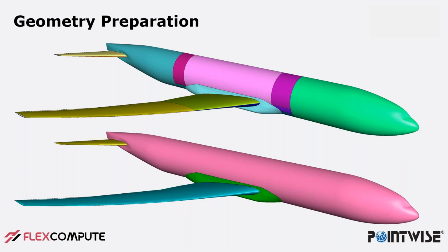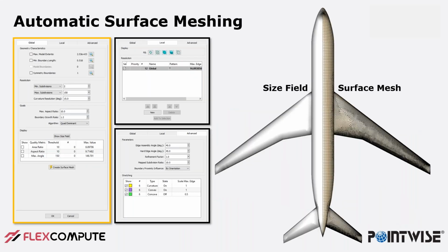Through solid modeling and quilting in Pointwise, we arrive at what you see on the bottom, where each color better captures the engineering intent, okay? We have a surface for the fuselage, fairing, wing upper surface, wing lower surface, areas where we plan on applying mesh attributes for control, but also applying boundary conditions for the solver. And this is really the prerequisite for the new Flashpoint surface meshing feature set for performing automatic surface mesh generation.